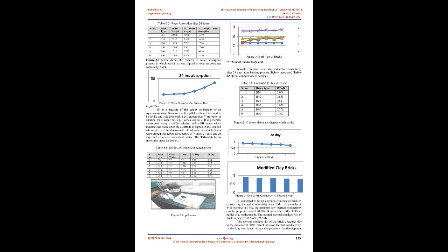J. Dimensional accuracy. The bricks so produced were tested for shape and size accuracy. It was found that up to 20 to 30% TPIS replacement, bricks maintained shape and size as per Class I brick standards, but afterwards they start crumbling from the edges and also lose shape. Discussion. The following observations can be drawn from these figures of test results for case A and B.